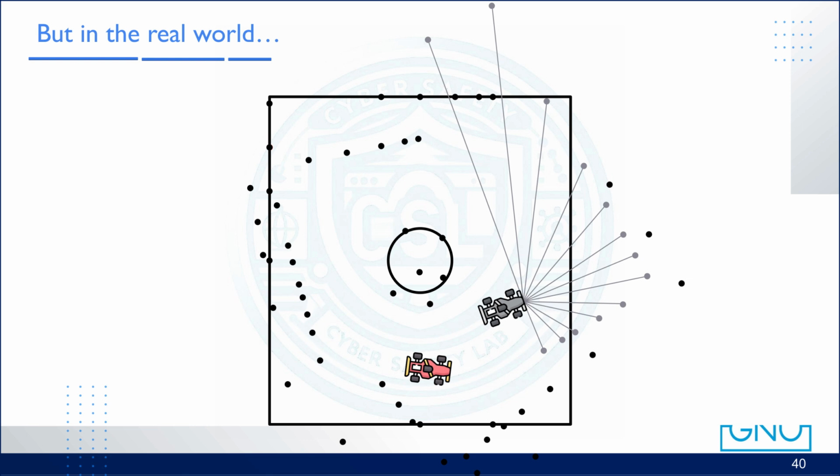When orientation errors occur, the distortion becomes even worse. If the robot mistakenly believes it has rotated more than it really has, the LiDAR points fan out in the wrong direction. Any small existing error grows dramatically.